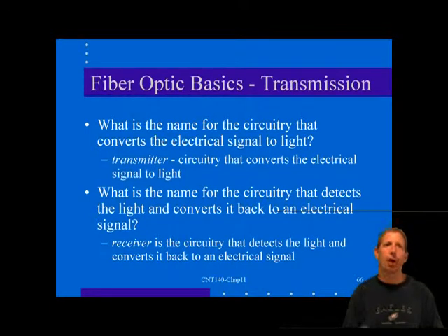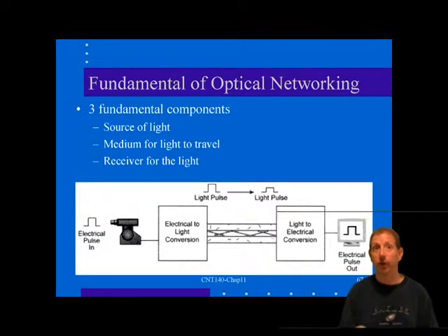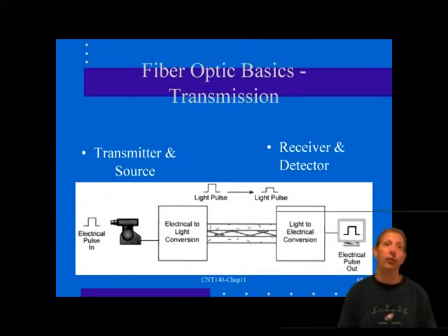Tight buffer cables are often used where a small number of fibers are to be pulled between 2 points without the use of a protective raceway. In these applications, the cable usually includes a tough outer jacket. The dual or duplex or zip cord type of cable is also used for patch cords, user cords, and jumpers.